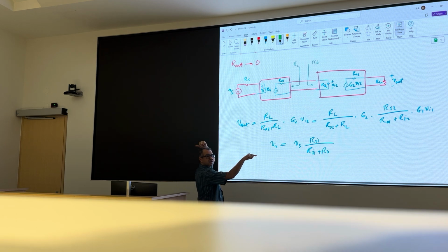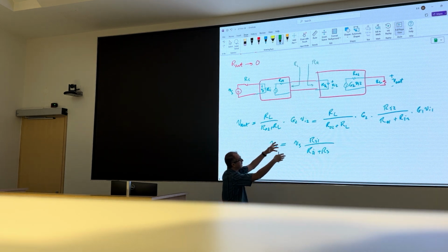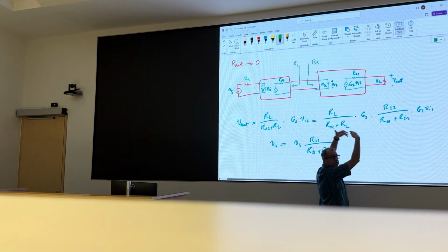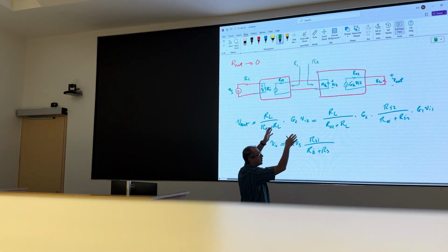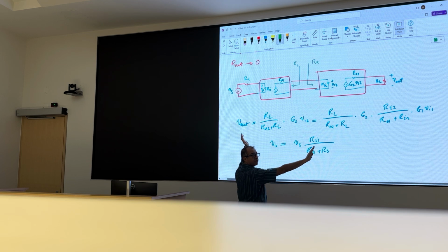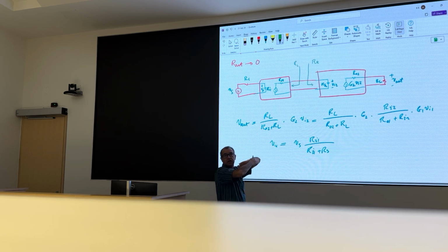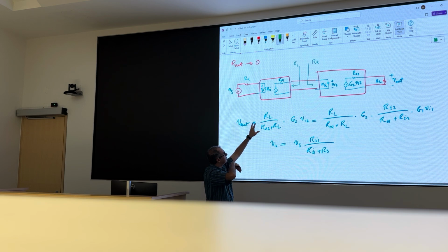What is the resistance that I see when I look forward? And then I can calculate this ratio. So in general terms, if I want to have an amplifier chain, I want to make sure that the resistance I'm seeing in front of me is much bigger than the resistance that I had before me, if the signal is going through that chain. But that depends. But I need to know.